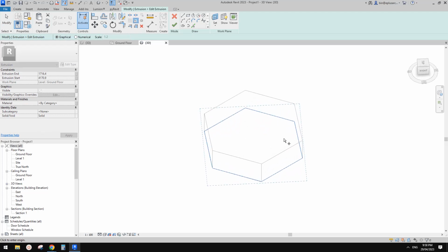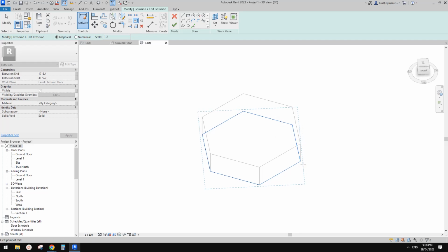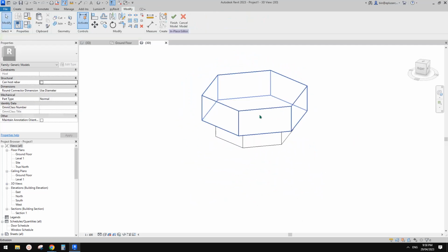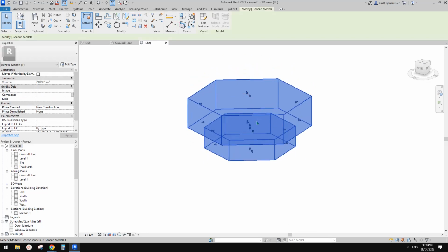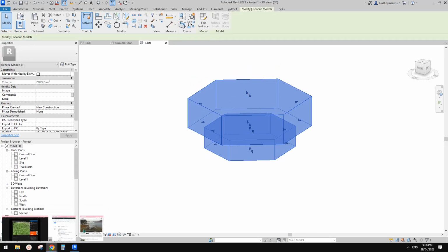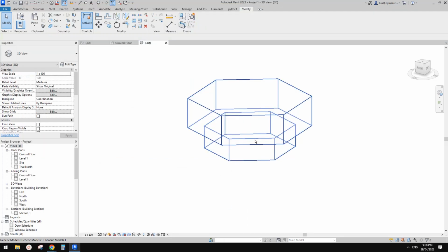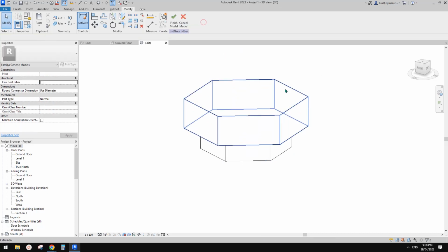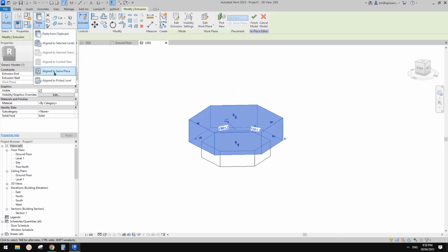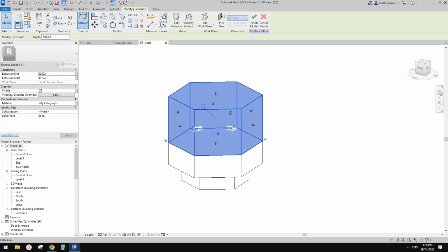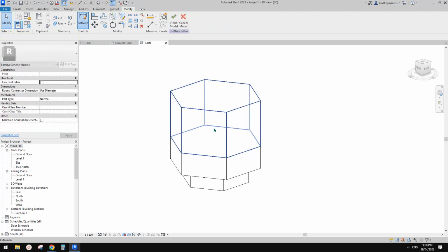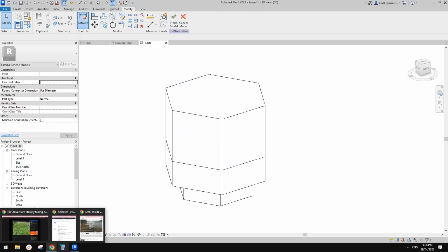So we can use, let me show how to pick the center point. Let's use snap to the midpoint of 2 points, and then we can increase the size. So just something like this to create a generic model in place. Okay, so you can see Control Z. So edit in place, Control C. We can just continue to add Control C, Control V, place in the same place, and then create those geometries.